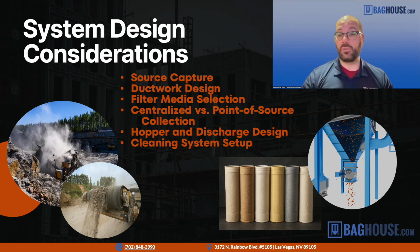And that doesn't mean that you have one massive dust collector that collects from all over the plant. It's generally better to have one collector for a certain group of sources. You know, maybe one to handle all the conveyors in one part of the plant or one room for example, or on the dryer, things like that. But those are still centralized systems in that they use the ductwork to pull the dust back to the dust collector. And then another common thing that needs to be looked at is hopper design.